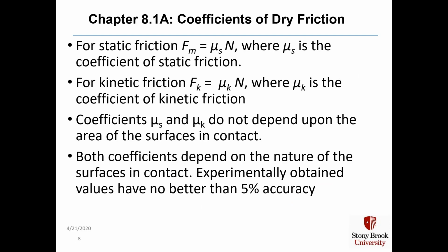For static friction, the maximum frictional force equals mu sub s times N, the normal force, where mu sub s is the coefficient of static friction. And for kinetic friction, F sub k is equal to mu sub k times N, where mu sub k is the coefficient of kinetic friction. Coefficients mu sub s and mu sub k do not depend upon the area of the surfaces in contact. Rather, both coefficients depend on the nature of the surfaces in contact, and experimentally obtained values tend to have no